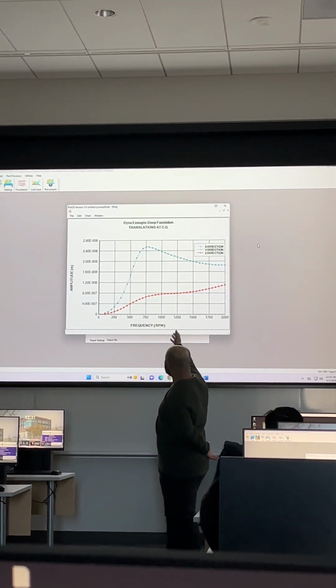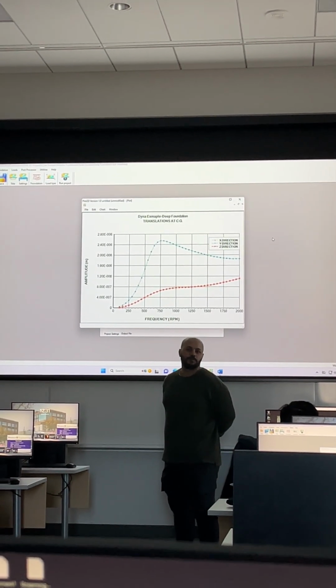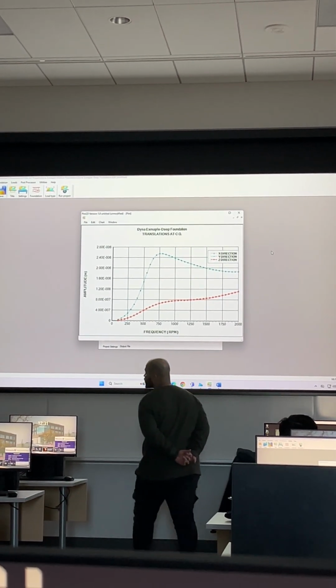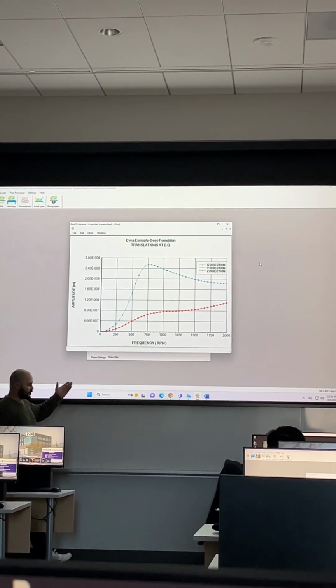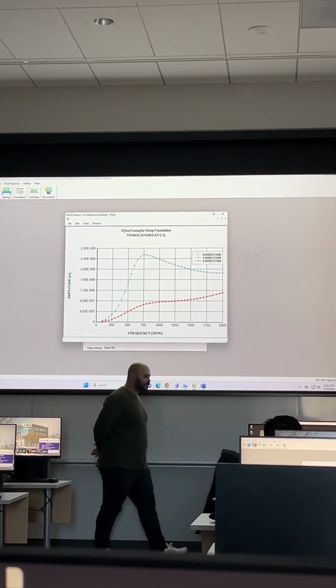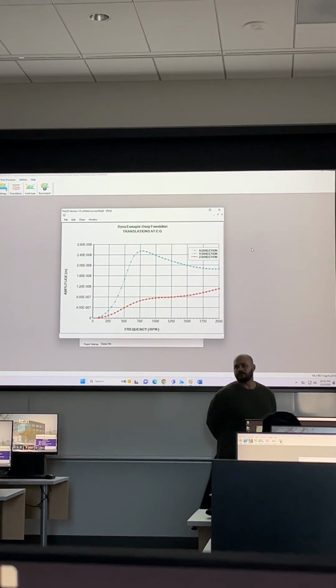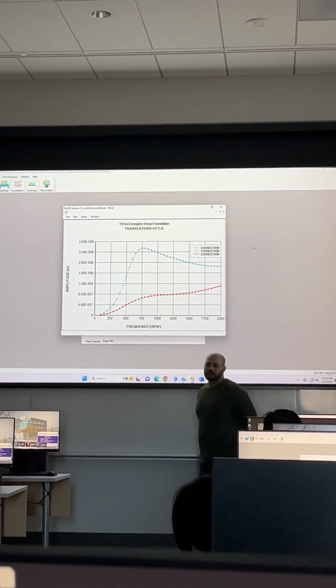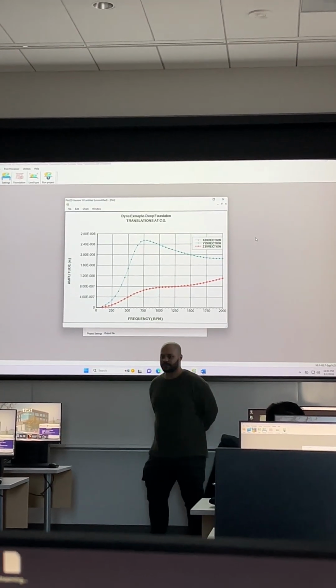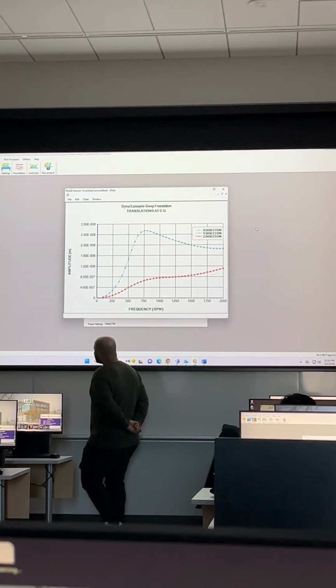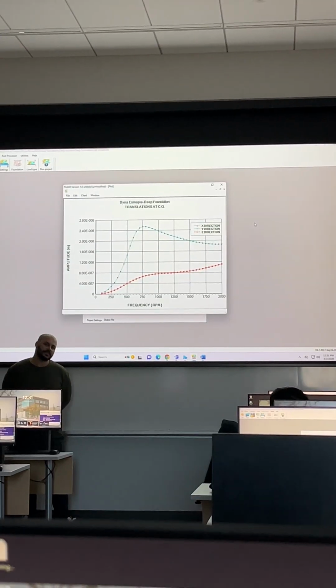So you can choose the response, the time-history response, and show which response is better for our case. And you can also try, as I told you, the side layer. This side layer will be granular fill or CLSM or something else, whatever. You can study all these cases.